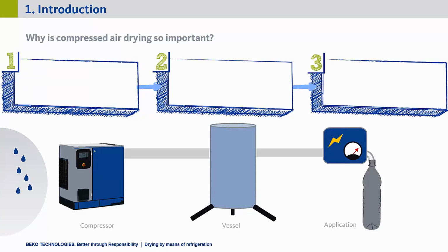In doing so, the compressor naturally compresses everything it sucks in, also particles and vapor, both water and oil vapor. The same amount of aerosols and particles, which do not cause us any problems in the ambient air or are not even noticed by us, quickly become our problem in a compressed air system, compressed to many times the ambient pressure, because we still have the same amount of aerosols, vapor and particles, but in a much smaller volume of air.